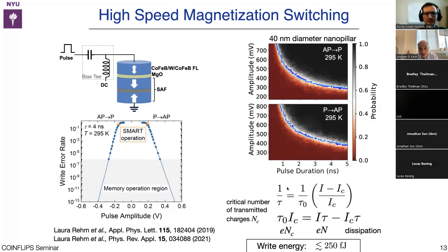And that asymmetry comes from both the magnetic fields that I told you about earlier, as well as the fact that the torques, the spin polarization, can be different from the two different geometries. You can have different amounts of voltage to spin current conversion depending on the direction of the bias voltage and the state of the junctions.